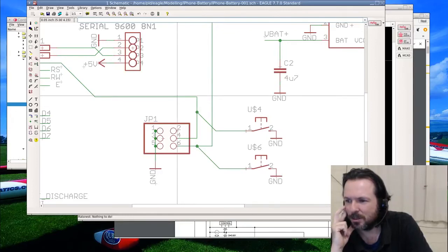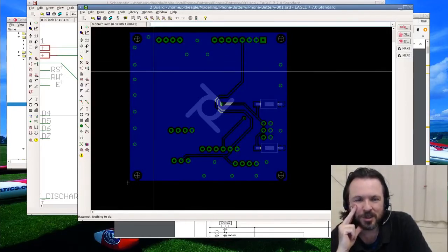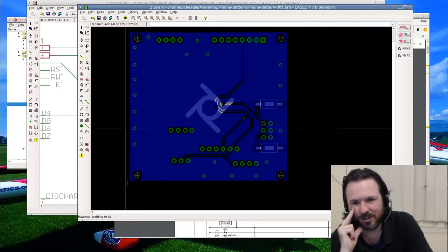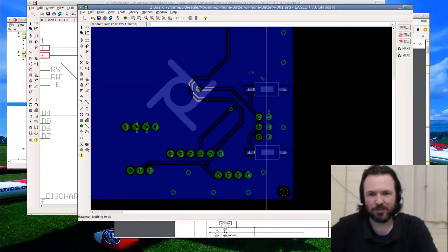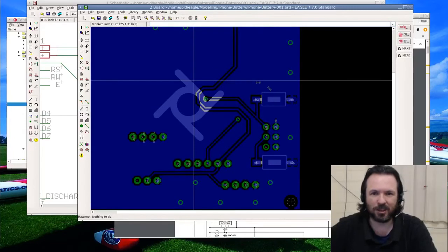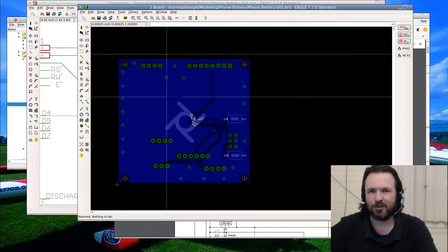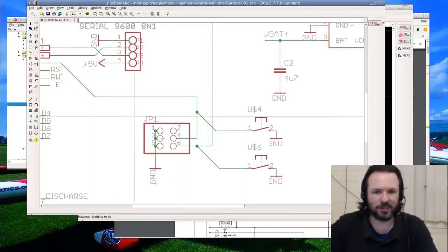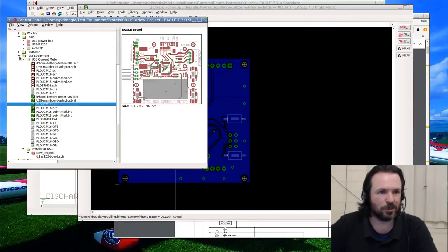Hey Tello, what tips do you have on designing such a board? I presume you're referring to this one. I don't really have any specific tips other than on your first revisions, start out the maximum size you sort of can within reason. I mean, obviously you don't want to have a board that's 1 foot by 1 foot. Except that you're going to have multiple revisions. If you try to get it perfect first time, you're going to live a life of misery. It just isn't going to happen. I mean, unless it's a really simple board. I've got a project that was all it was a 5-volt regulator with an alarm on it. And I have got so many revisions of that thing.